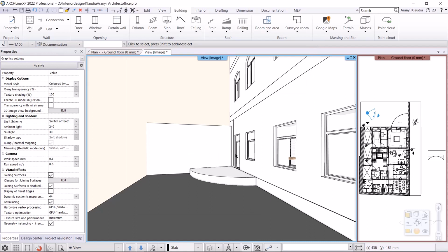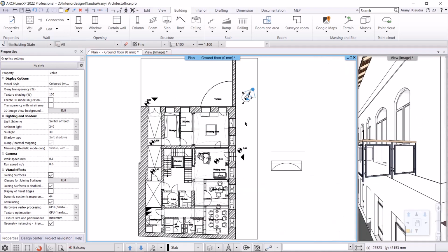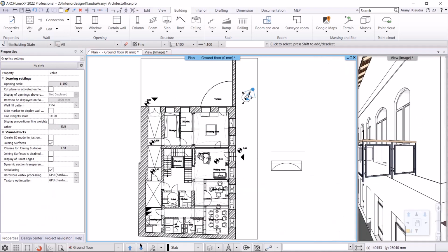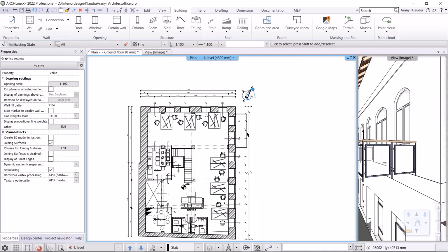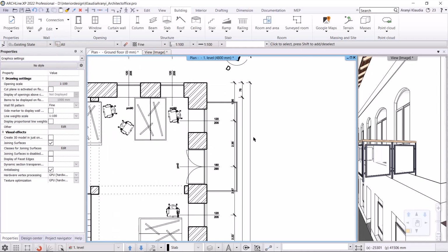The next topic is sloping and variable thickness slab design, which I will show on a balcony slab. For the balcony I will use slab layers. I will switch to the balcony view in 3D. I will make the slab on the first floor's floor plan. To do this, I move to the first floor. The balcony contour is already drawn and the railing is already formed.